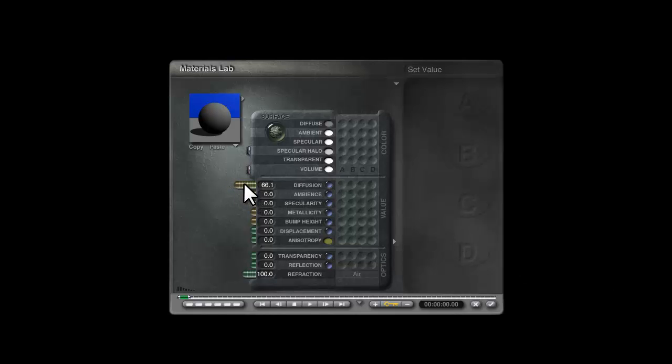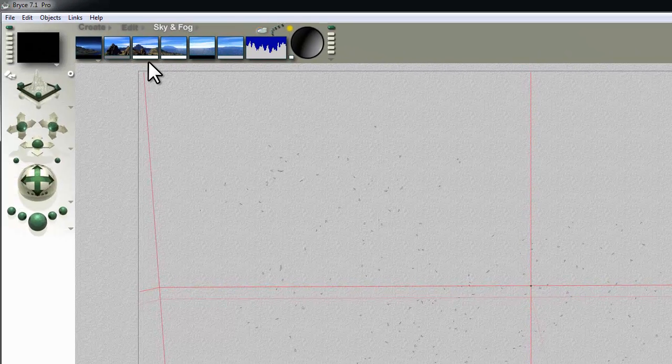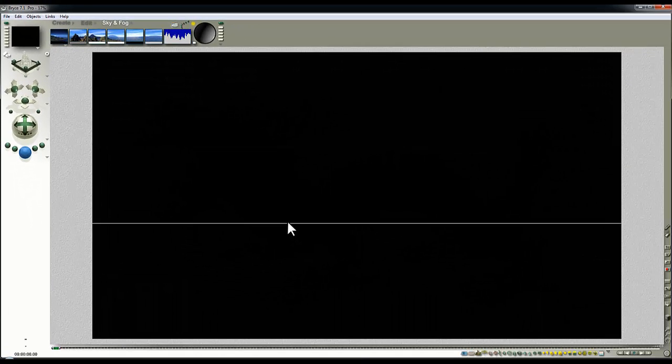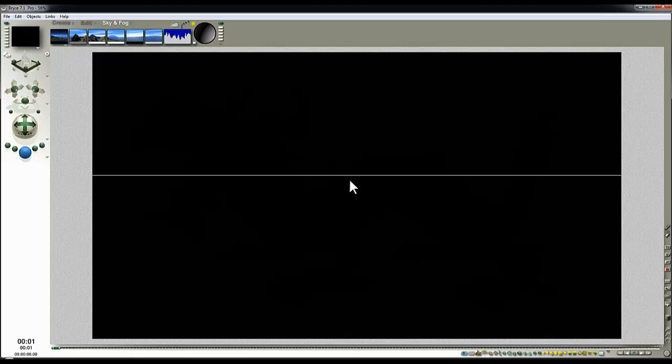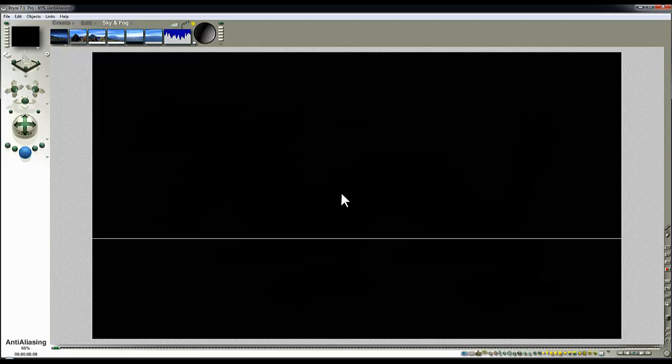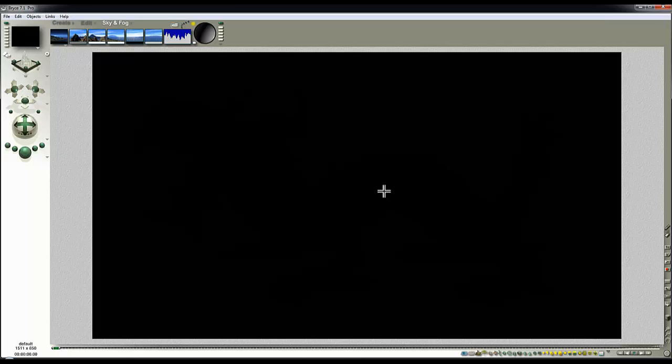Now I'm going to modify the material of the cube, which is still selected, so that it has no diffuse and an ambient output of 1. So that's ambient coming from this channel, which is white, and from the global ambient, which is currently grey. So as things stand, it would be very difficult to detect the difference between the dragon's colour, which is black, which I don't even know if that counts as a colour, so that's just black, and the very, very slightly grey colour of the inside of the cube that's being lit by this ambient channel.